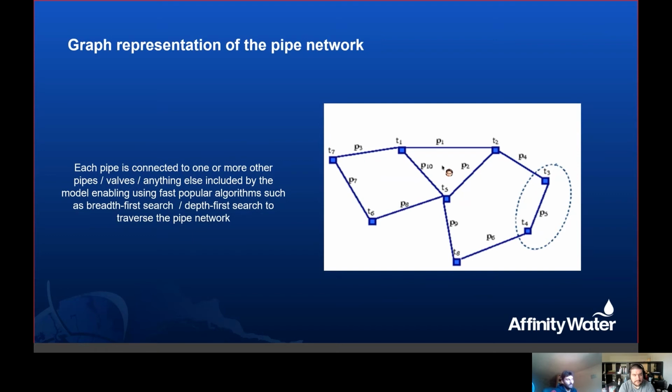We model, as part of this, the pressure and the flow in the pipe: which direction is the pressure, which direction is the flow, what's the exact pressure on this particular pipe versus that particular pipe, even if there's no logger around there. We can also see what the soil is, when the water is going up here, going downhill, etc. And then finally, after we have our X and Y, we can build the machine learning models.